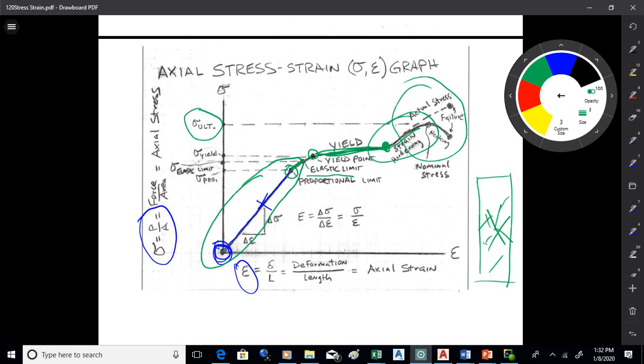Yeah. So if this represented just like a piece of the truss in a bridge, over time, could you use this to determine how much time it's going to take for it to fail? That's another test, and that's repetitively loaded. That's cyclical loading. And you can get cracks and things that form in a material if it's been strained and then the strain's released over and over again. You're basically strain hardening the material when you do that. But could we analyze it in a way to say, in this many years, it's going to be at this point in graphs, we need to replace it?